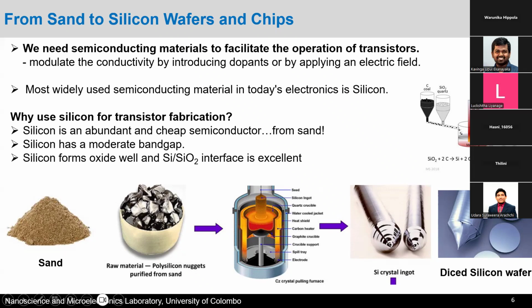So what you can actually do is you can do this over and over multiple times, and also get rid of certain other impurities in silicon, and you can then get extremely pure silicon nuggets purified from sand itself. And once you have the silicon nuggets, this is called polysilicon because silicon has a particular crystalline structure, but these crystals are mixed up in certain ways, and it's not one single crystal in these nuggets, right? So you have polysilicon crystalline, as we call it.